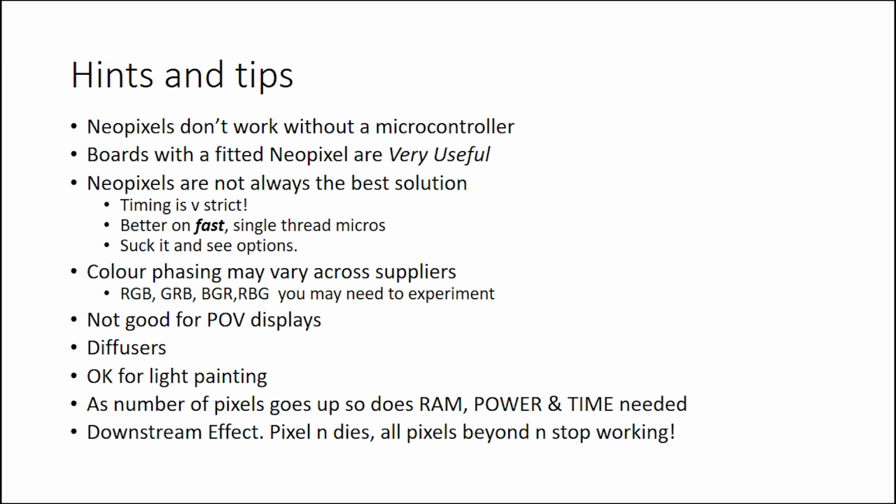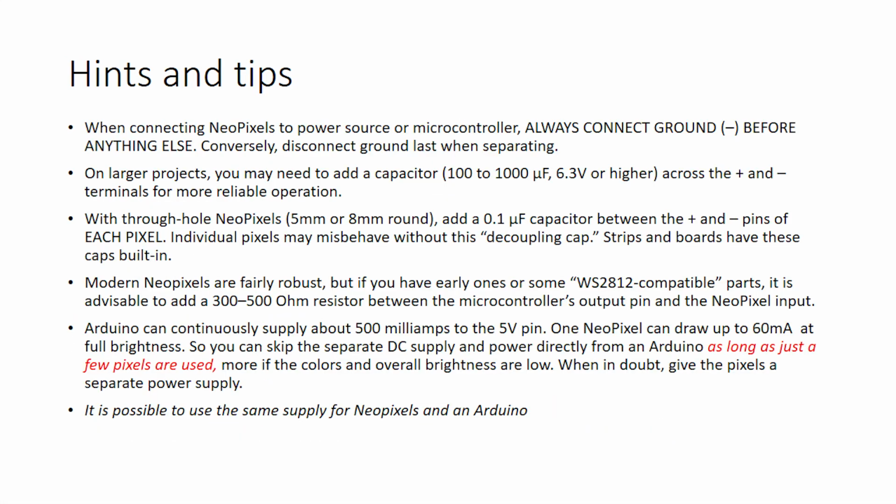So lastly, some hints and tips. Because of that overshoot problem, always connect the negative before you connect anything else. So you connect the minus wire, the ground, and then you connect the data and the plus. You don't connect the plus first and then the data. Bad things will happen, you will regret that.